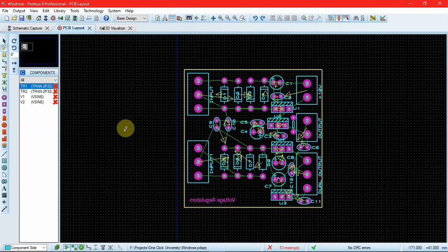In this video, we'll be studying the trace selection procedures from step 1. So, first step, after making the board edge, that is the mechanical outline, and placing the components, is you have to decide how many layers you have to design this PCB with to avoid the various noise issues such as electromagnetic interference and so on. Also, to make the circuit compact, on how many layers would it be feasible.